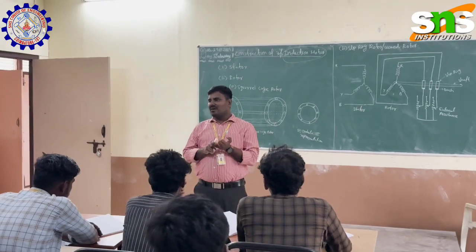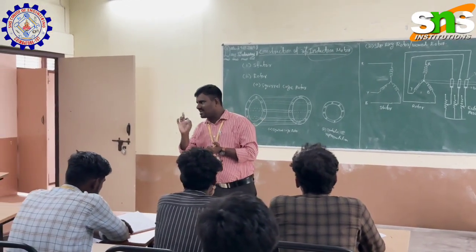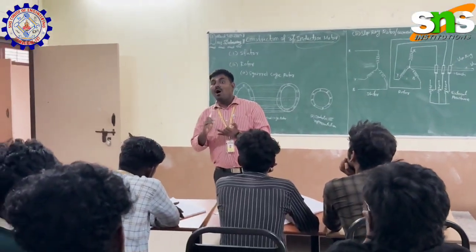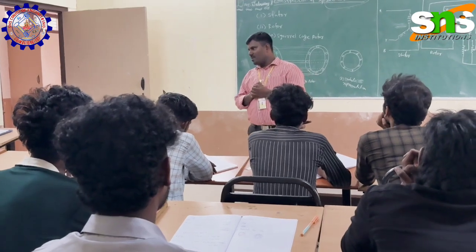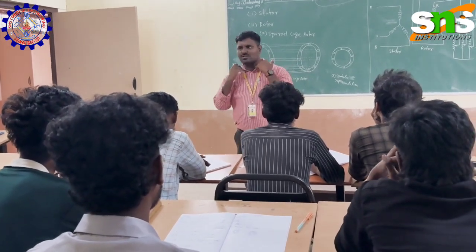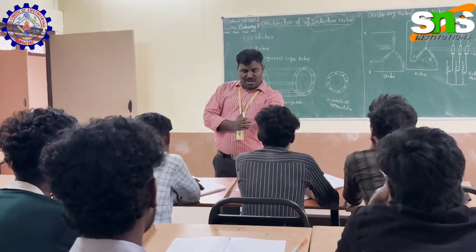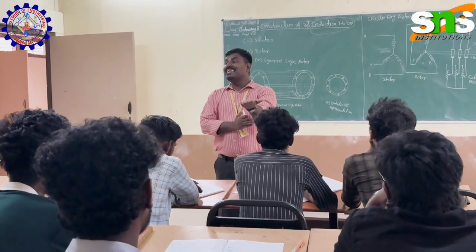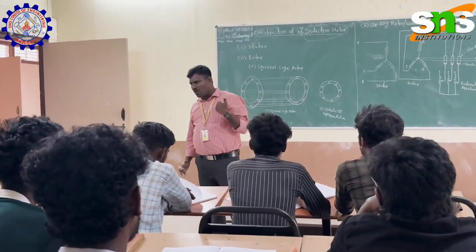But in the induction motor, we give the power supply only to the stator winding. Automatically, the EMF will be induced in the rotor winding. We are not giving the power supply to the rotor, but the rotor induces some amount of EMF because of this induction principle. That's why it is named as induction motor.